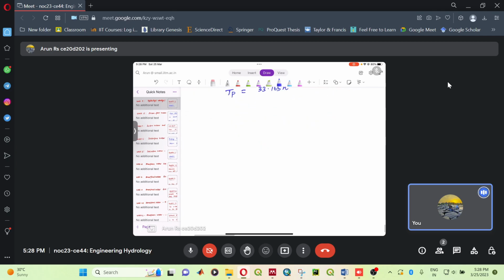Next we'll be distributing the width at 50% and 75% by a rule, that is 1/3 will be to the left of the peak and 2/3 will be to the right of the peak. So we are calculating the ordinate for that. So this will be 23.635 hours.